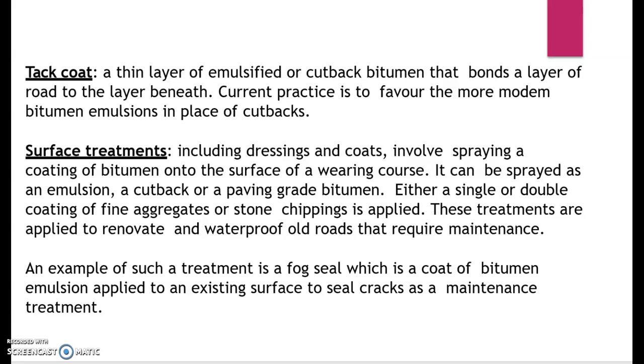Emulsion is produced by mixing asphalt with 50 to 60% water in the presence of 1% emulsifying agents. When the water evaporates, the emulsion breaks and forms a waterproofing layer. This can be applied in cold condition. That is asphaltic emulsion.